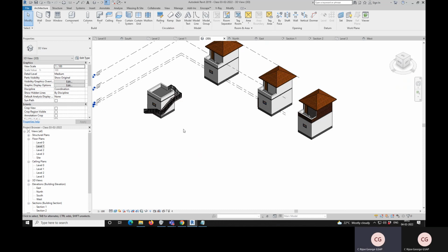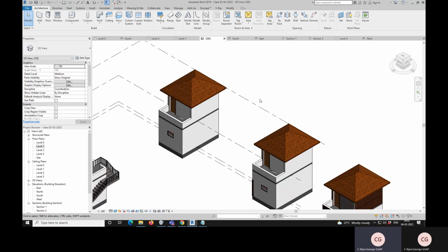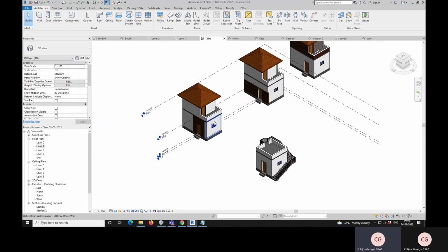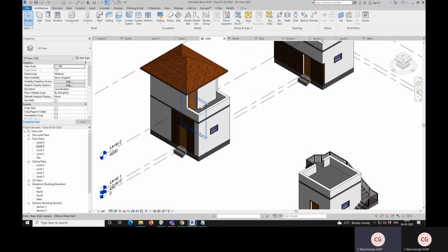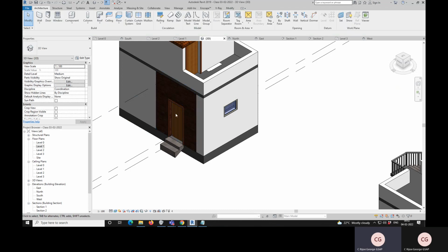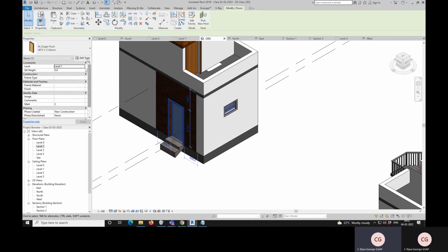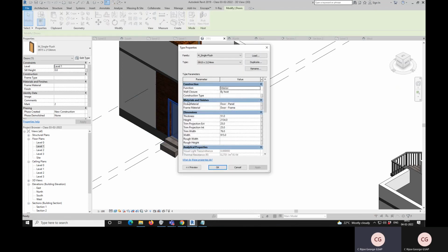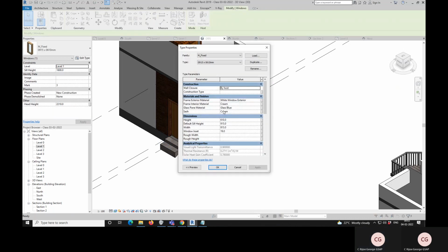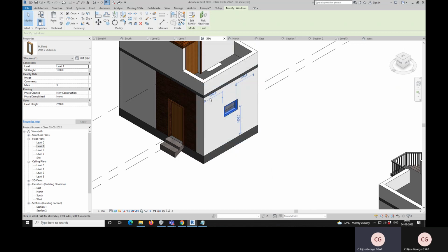So that is what I had to teach you in this class. And I think I have things very clear. I taught you how to create a material, how to apply it to a window, each part, how it is seen. For example, select a door, where it is seen, component level, you go to edit type. There you have material. Any object selected will have materials and finishes.